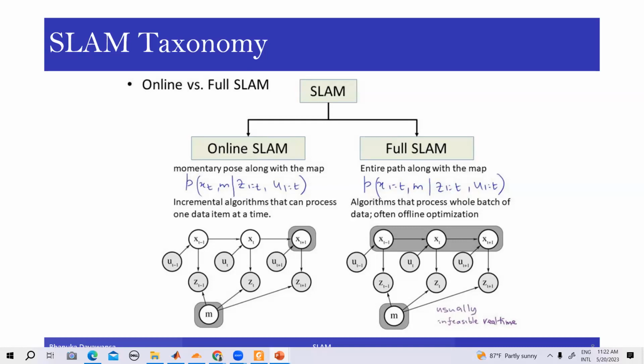So it constructs a map of Mars or the moon or whatever, in the satellite or in the space station or the control station on Earth. The full SLAM is not done in the robot, because there's a lot of processing power needed, and it is a multi-sensor platform with so many sensors giving so many inputs. It can't allocate a lot of space, and its computation capacity cannot be wasted on that. So what it does is a local, online SLAM in position, and gives the full SLAM model to the controlling area, right?